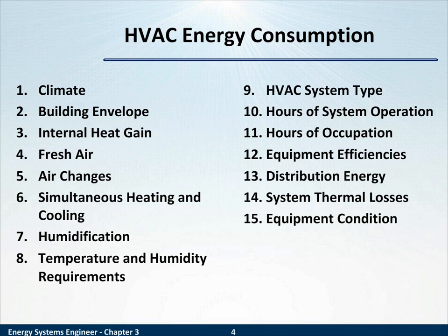Temperature and humidity requirements in a space. Of course, the set points affecting the energy consumption. The system type and hours of operation. The hours the space is occupied. Equipment efficiencies. The energy distribution requirements. System thermal losses, duct work, piping, and so forth.